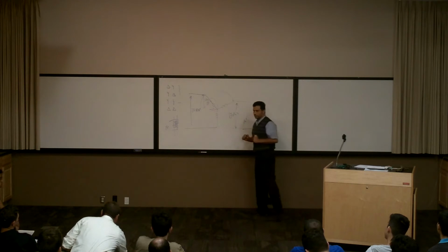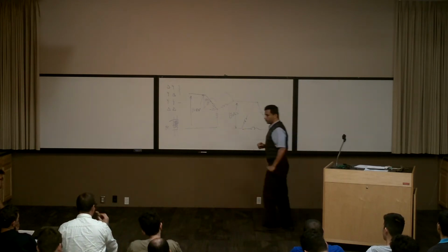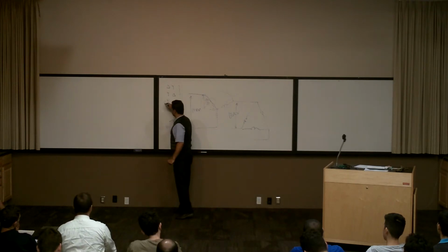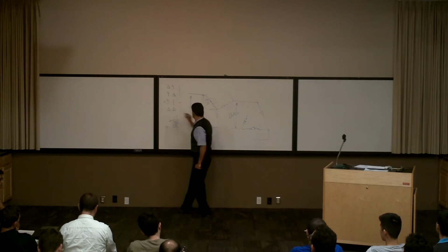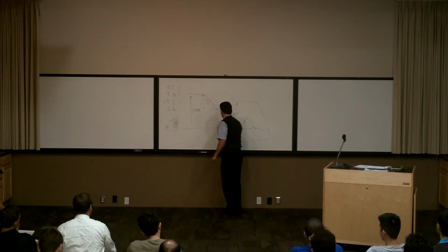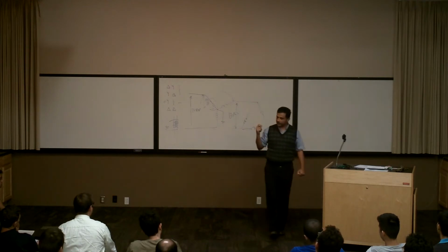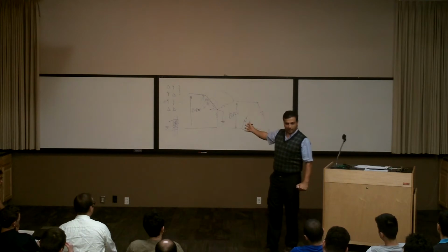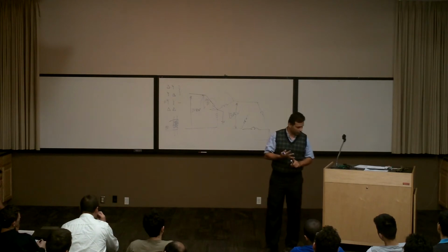That's the main advantage of the Y connection. The other advantage of Y connection, usually, they put it like this. For example, they say grounded, the middle point is grounded, somehow it's connected to the ground. Y connection could be with ground or neutral or without. So with the ground or neutral, it's going to give you the fourth wire. So you can supply single phase loads, right?